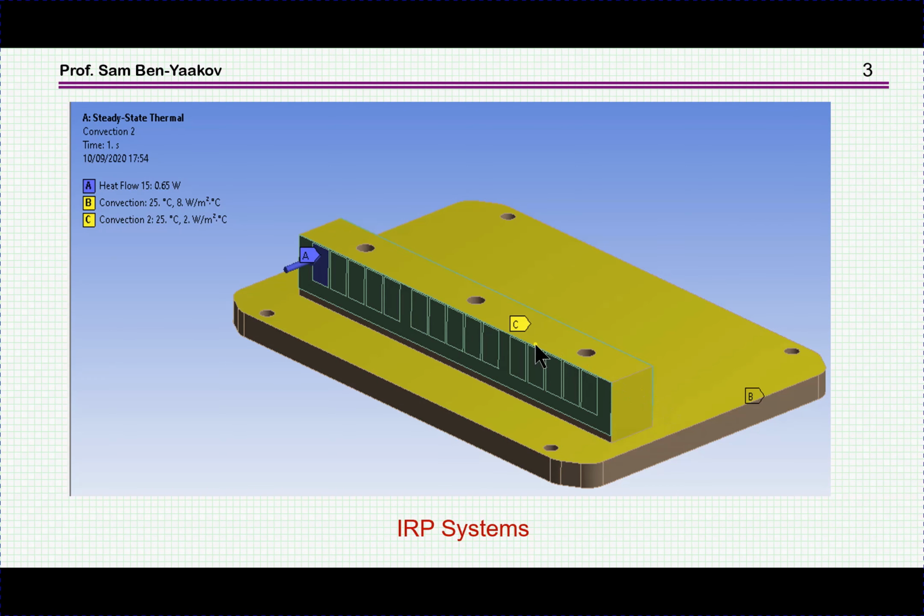To remove the heat, we do need some cooling fixtures. And here is a simple block. This is like a heatsink without fins in this case, it's just a plate. Here is a block of aluminum. Here are the transistors which are attached to this block, and the heat is passing from the transistor to this block and then into this plate and then dissipated outside to the ambient.